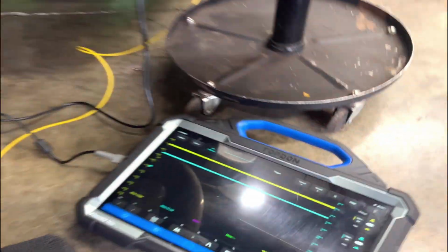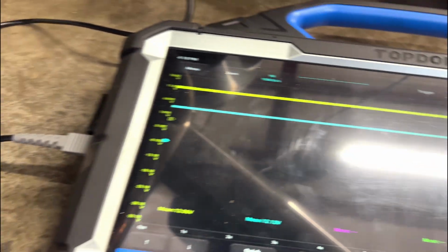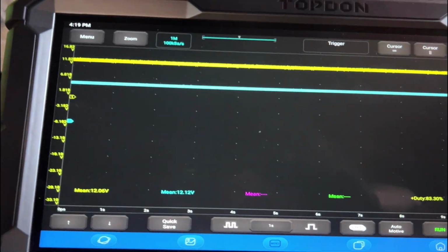Transfer case control module is behind and above the body computer. Here's the body computer, and that blue lead right there goes to that box, and that's our transfer case control module. Our scope leads, we're at 12 volts on both of those. Now let me roll under. All right, now we are back probed in. I'm going to disconnect this. We still have our 12 volts.